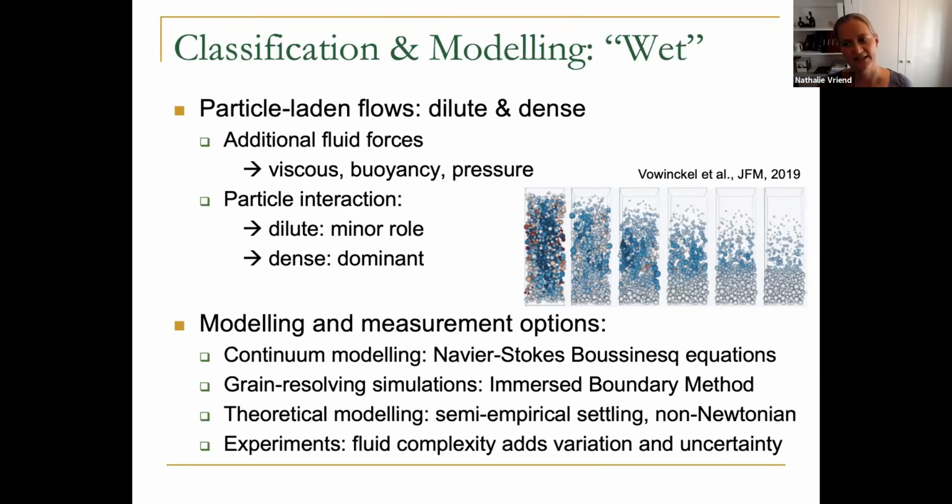So as the particles settle down, you can see a very dense phase at the bottom. So here, if you think about particle interaction, it's definitely dominant in this dense phase, but even in the dilute phase, there may be still a minor role for particle interactions. But if the fluid is there, we have additional fluid forces like viscous forces, buoyancy forces, pressure forces.